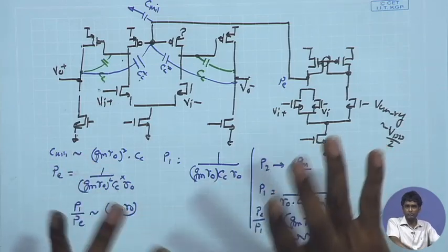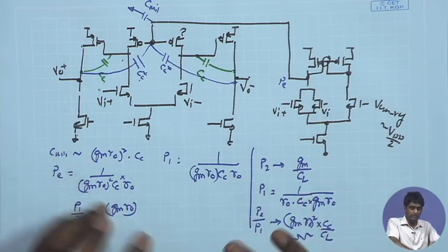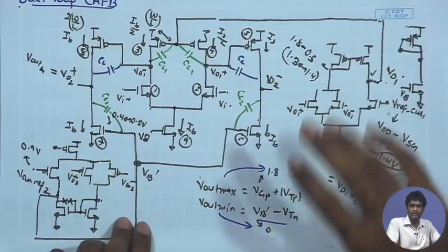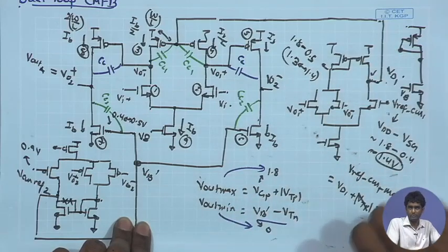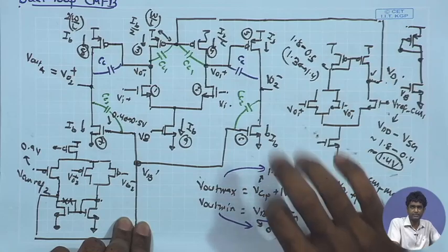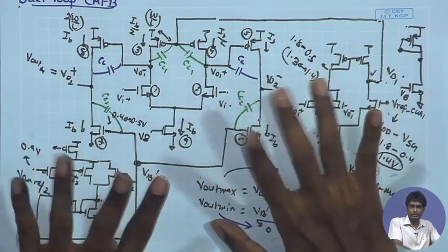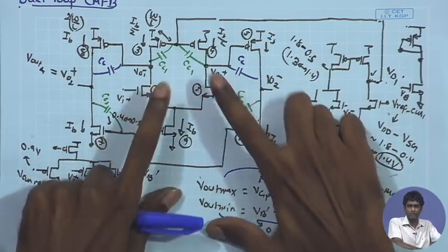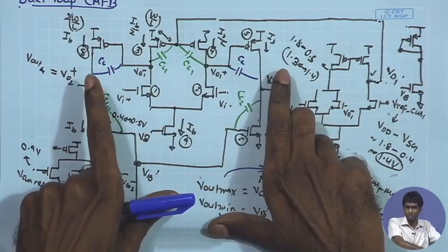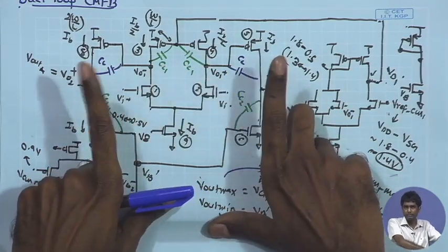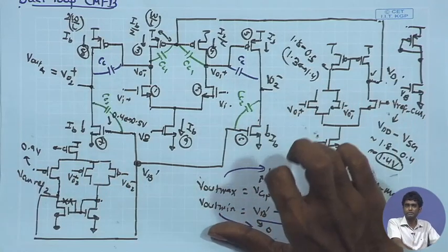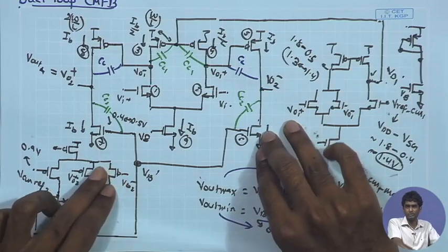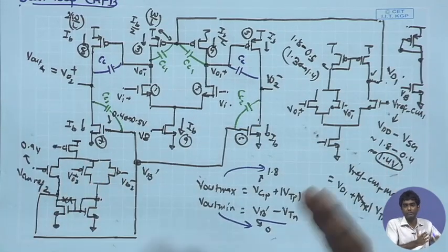For the DC biasing point also, you should be aware of the kind of amplifiers to use whenever you are requiring feedback, kind of topology to use, whether you use a PMOS input device, NMOS input device, what kind of DC biasing to get for references, etc. And then when you are looking at multiple loops, how to look at their interaction, whether the compensation in one loop is interfering with the compensation of the other loop, whether the compensation of common mode feedback is interfering with the differential compensation. Those things are important to be understood, so that you can appreciate what is going on in the simulation, and you can in fact check those effects.